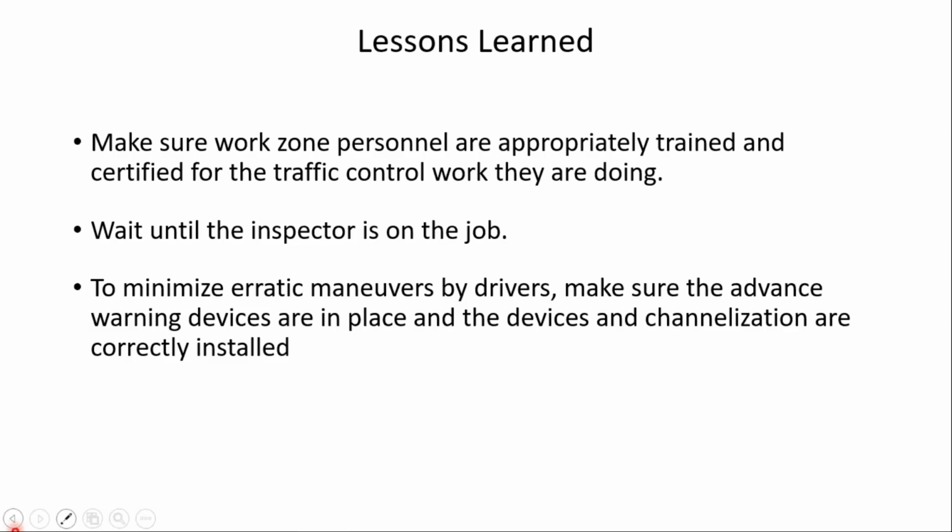But to minimize erratic maneuvers by drivers, make sure the advanced warning devices are in place and the devices and channelization are correctly installed. And in this case, I think the taper was too short, but probably more significantly, the arrow board was not placed at the proper location and there was no advance warning. So overall, this was not a good situation. But any questions or comments anyone has on that example?